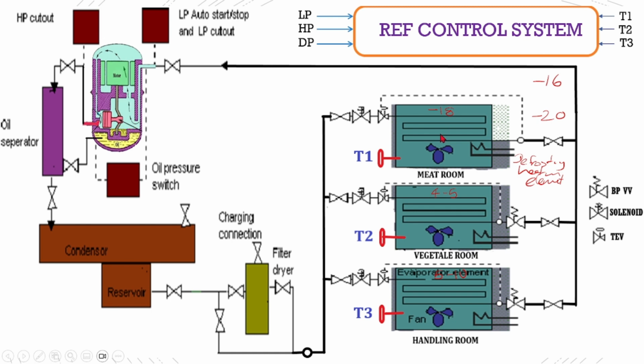At the same time the room is reaching its upper cutting level, the temperature. At that time, because of the sensing, as this line gets cooler and cooler, the expansion of the gas or the liquid in the sensing bulb will reduce, and the expansion valve will gradually shut down, so closing, right? As the expansion valve closes up, the suction pressure starts to fall down.